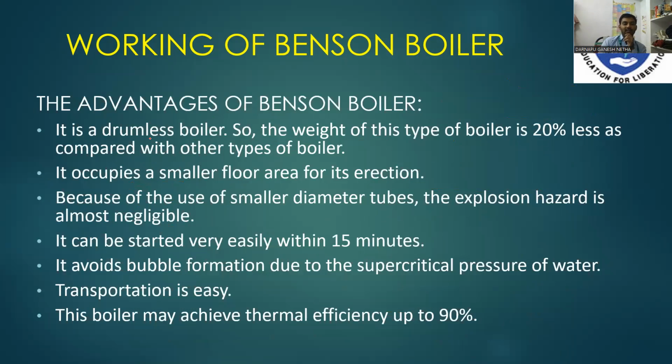Advantages of the Benson boiler. It is a drumless boiler, so the weight is less compared with other boilers. It operates in a smaller floor space, and its erection is easy. Because of the use of smaller diameter tubes, the explosion hazard is almost negligible. It can be started within 15 minutes. It avoids bubble formation due to the supercritical pressure of water. Transportation is easy.